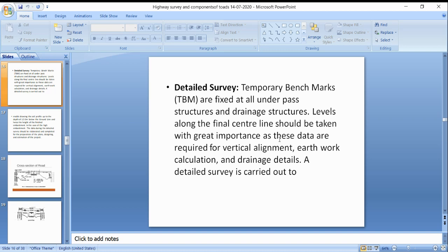If there is no chance, then we have to go for other probable routes. If the maximum flood level and the water capacity of the ground are more, then we have to spend a lot of money, so the cost will be more. Instead of that, we have to deviate to another proposed route.